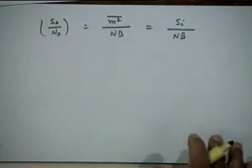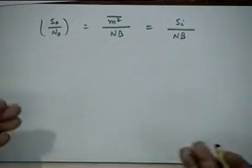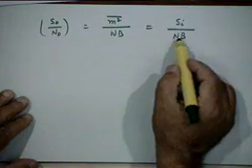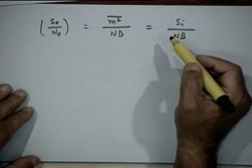Noise power spectral density is N by 2, right. The amount of noise power in the bandwidth of the message will be N by 2 into 2B, because the baseband signal has a bandwidth of B, or on the frequency axis from minus B to plus B. N by 2 into 2B gives you the noise power in the message bandwidth. So, once again output SNR is the same as the input SNR.